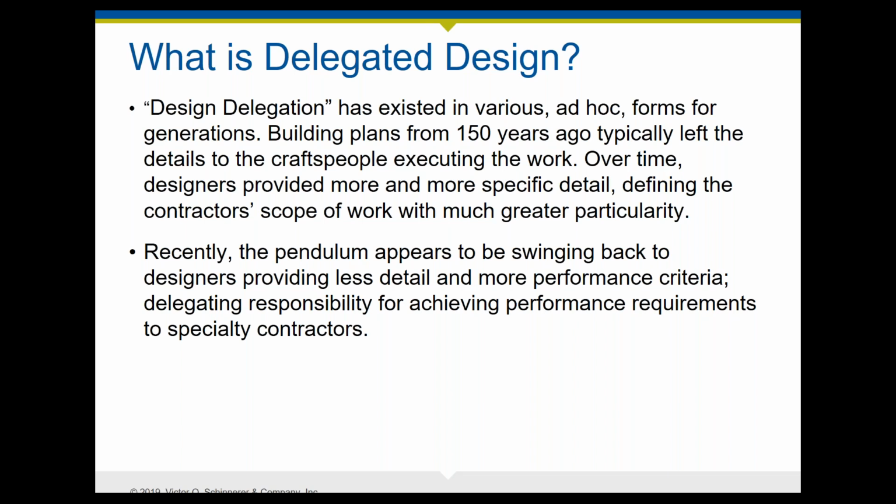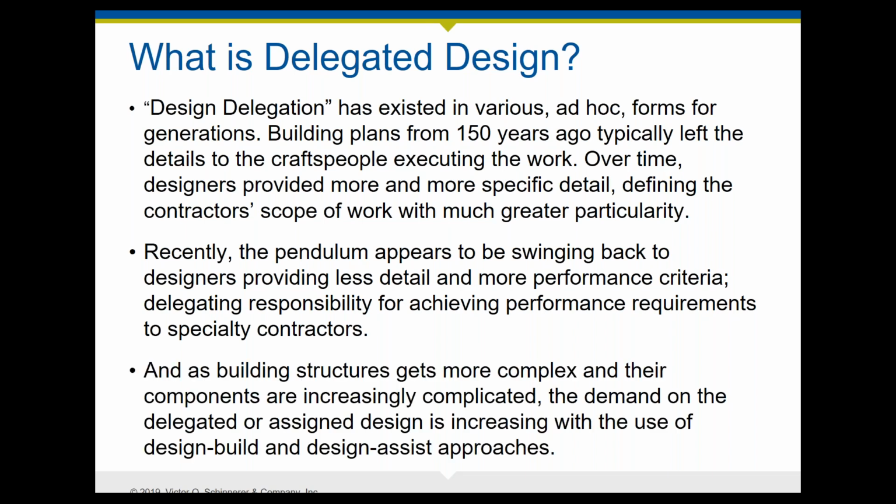And for reasons of cost in projects and complexity or specialization, or even the use of BIM, there seems to be more situations where designers are delegating responsibility for achieving the performance requirements to the general contractors, or through the general contractors to specialty contractors. In fact, a survey recently said that there's probably 100 scopes in the design process that have been delegated or could be delegated to contractors and especially subcontractors. And that's often structural steel connection details, curtain wall panels, metal framing systems, roof trusses, stairs, handrails, guardrails, a number of things like that, fire suppression systems. And in fact, I think there's very few engineers anymore who design sprinkler systems. That's usually a delegated design situation.